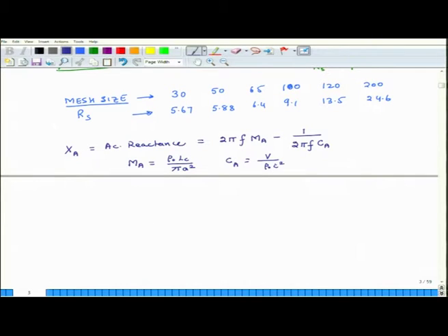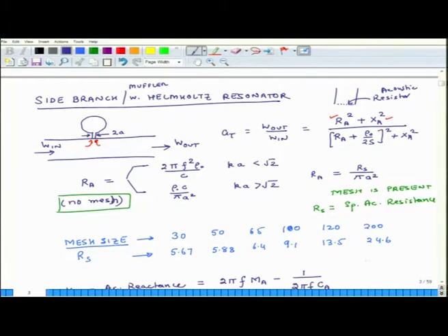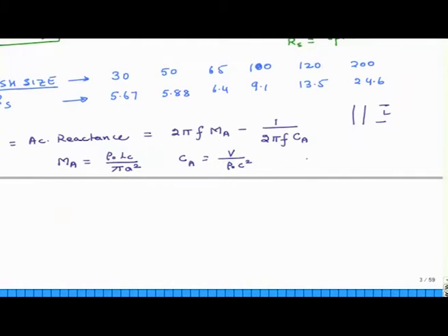And what is L C? If the tube is L long, L C is the effective length of the tube, and that is equal to L plus L A plus L B. And if you remember last class's lecture, I had said that as air passes through this tube, there is mass of air inside the tube, but it also has to oppose some mass of air at this end and some mass of air at this end.